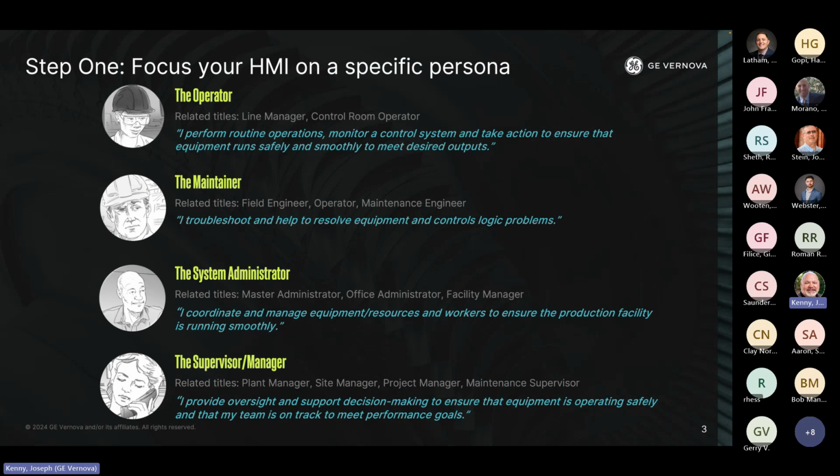One of the things I like to talk about, and I won't belabor this slide, is that when designing the HMI, folks have to look at the different personas they have. These are very common high-level personas. But one of the common mistakes when designing an HMI screen is to say, well, we'll design the screens for all the personas, so the screen will work for everybody. That is not high-performance HMI.